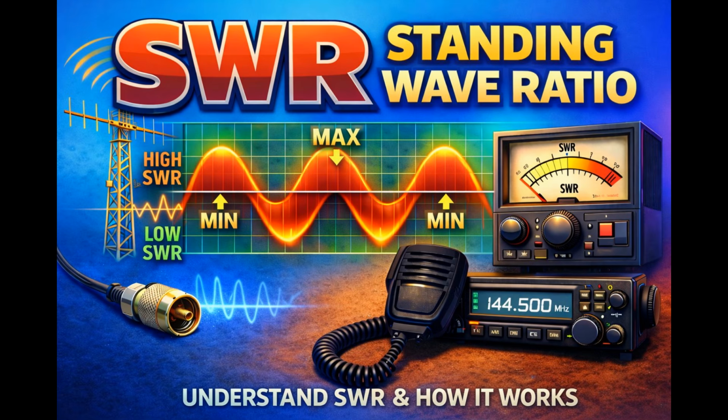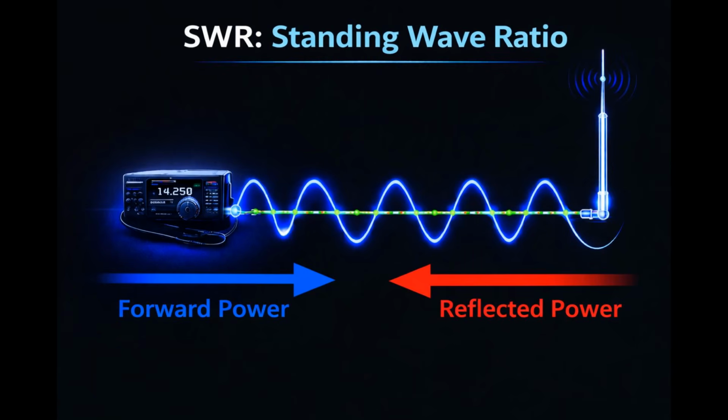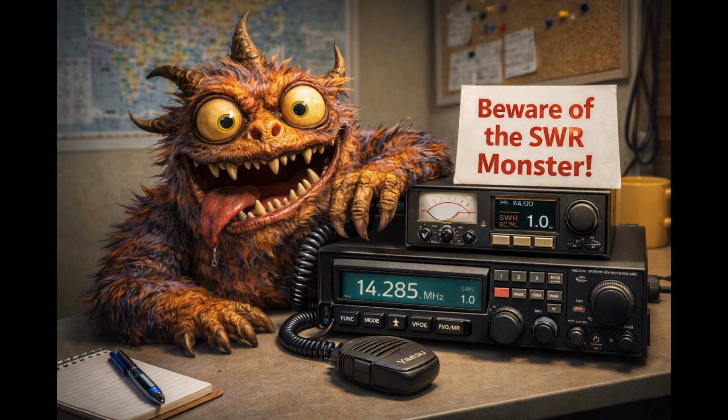In this video, we're going to introduce standing wave ratio, or SWR, and explain what it means in a simple, practical way. When your radio sends energy down the coax cable toward the antenna, that energy is supposed to leave the antenna and become a radio signal traveling through the air. If everything is matched well, most of that energy goes out as intended. If not, some of the energy is pushed back toward the radio instead of being radiated. SWR is the measurement that shows us how well that energy transfer is happening.